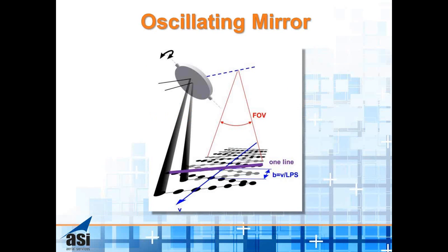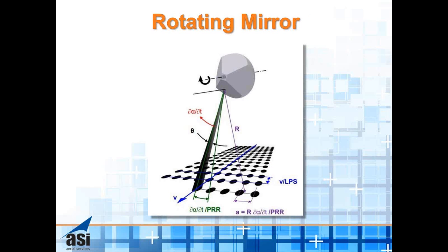The equipment that we use, there's a couple of different kinds of sensors. There's an oscillating mirror. The oscillating mirror works in a zigzag pattern. When you think of a pendulum swinging back and forth, that's basically how the oscillating mirror works. So it's going to derive its data in a zigzag pattern. The problem with it is that it can slow down and then stop to change directions to come back the other way. Sometimes that creates bad data, so a vendor may take bad data and then overlay it on top of the other bad data, so they'll do a 10% overlap and trim the edge.